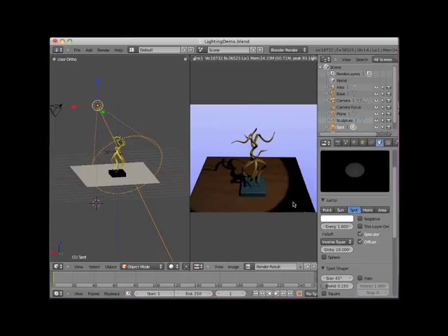The spotlight has a sphere attenuation checkbox, which limits the extent of the lamp's light beam to a distance setting. The shape of the beam is still a cone, despite the name of the sphere. Unlike fall-off, the sphere's attenuation progressively limits the intensity of the light to total darkness. In other words, there is no light beyond the extent of the distance setting when the sphere checkbox is checked.